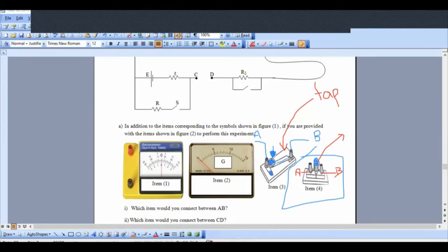So the difficulty with the tap switch is you have to always push it downward to keep it. The amount of current flowing through a closed tap switch depends on the pressure applied on it. The pressure applied by the finger determines the resistance of the switch and the current flowing through it. So if you use a tap switch, we will not be able to obtain a constant current. In potentiometer circuits, the current in the potentiometer wire should be constant.